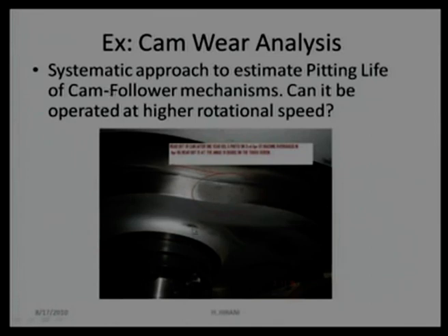If this cam was operated at 60 rpm, can I think about operating at 65 rpm? The benefit is that faster filling of the toothpaste will happen, and if we are able to gain 4%, 5% production, that will overall give good returns.